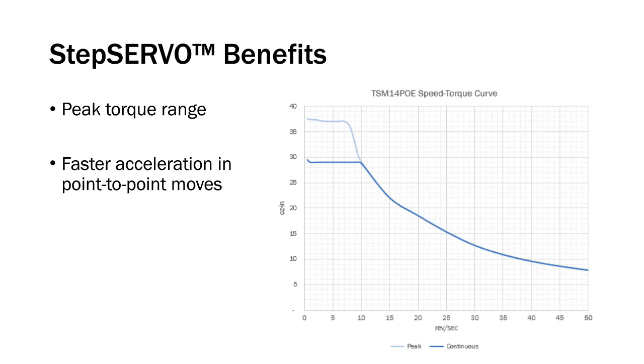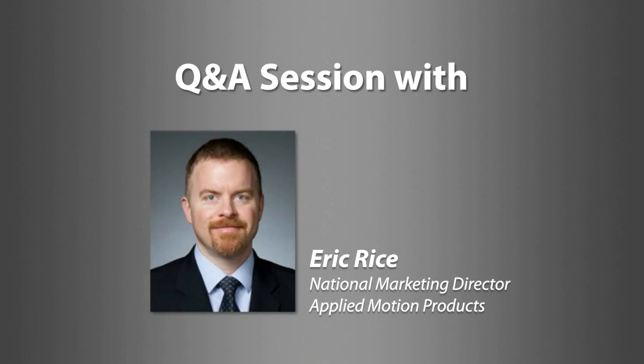And how fast can the motor run? So step motors are an interesting little animal in that their torque drops as speed increases. So the answer to that question is always, how much torque do you need at what speed? If you don't need a ton of torque, that's where you have to look at the speed torque curves. If the torque you need at full speed falls within the curve, you can run 2,000, 2,500, even 3,000 RPM. But if you need all the torque that's available down in the low end of the torque curve, obviously you don't have that at the high speed.